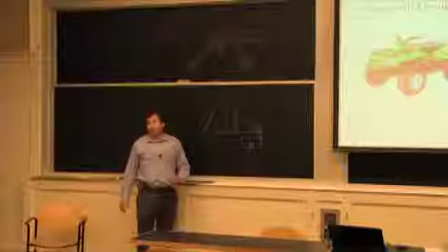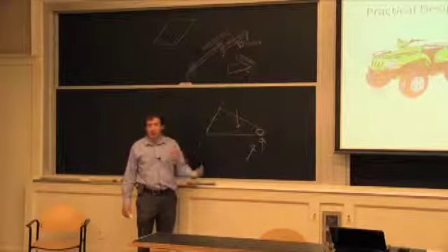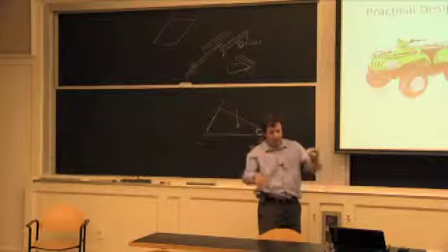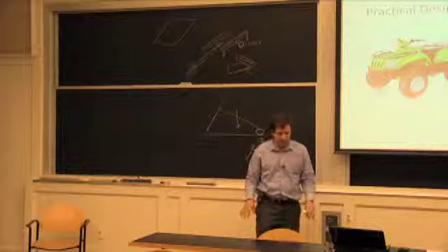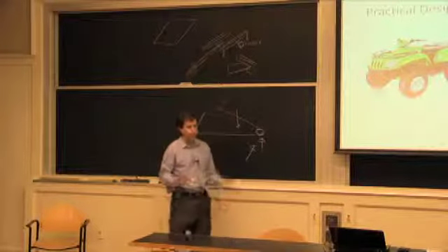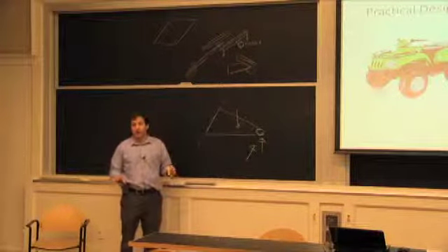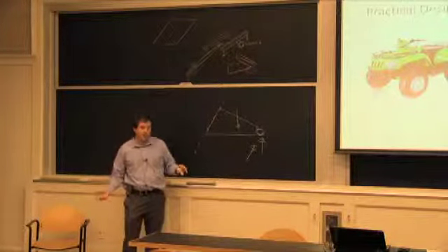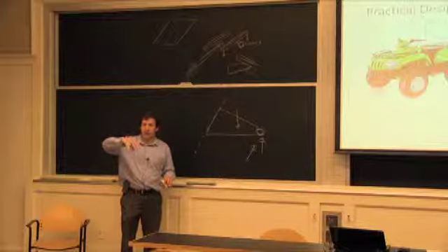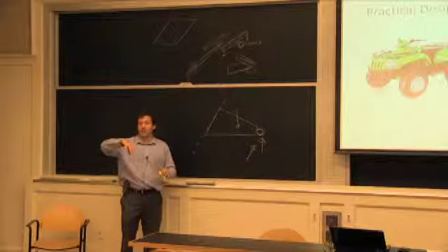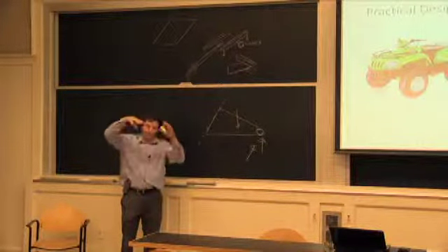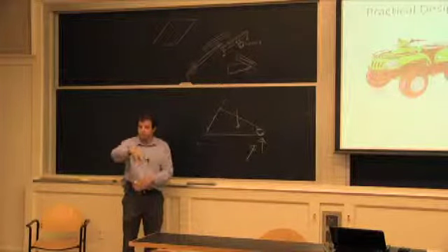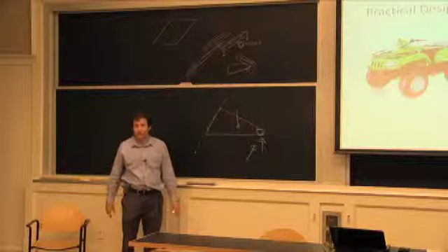It's a complex loading, and when you think about those rubber wheels going around a rough terrain, you can arrive to worst case scenarios. It's really hard to put more than the whole weight of the vehicle on one wheel, because if you start really putting a whole lot more than that, it means you're landing really fast on one wheel, and that would typically get you to lose control.